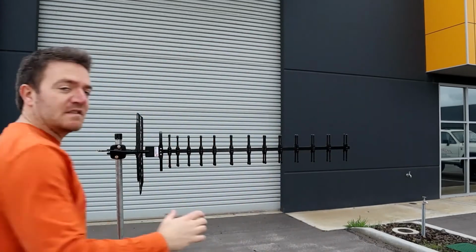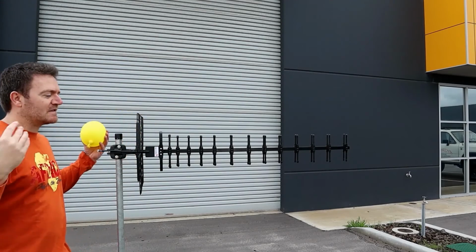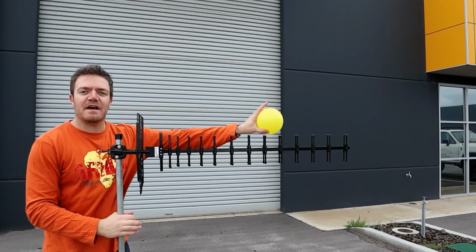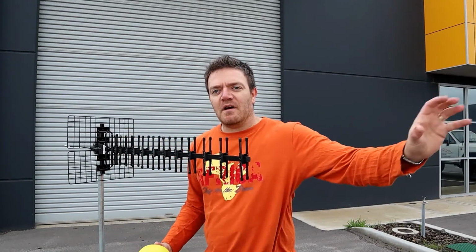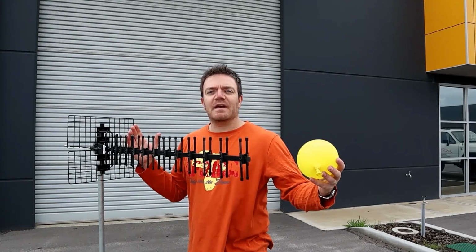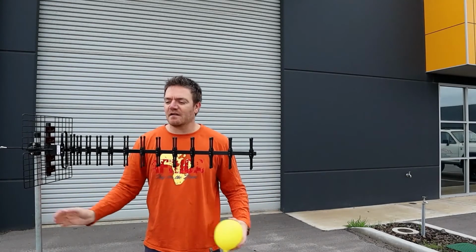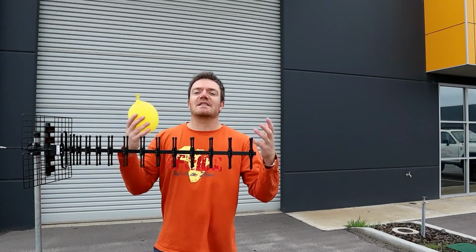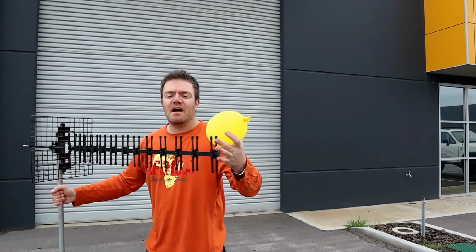Sometimes it's just long elements at the back, but the concept is that the antenna by itself, if you stand on this side, there's not much happening. So this is pointing away from anything sensible. This is the back, so I don't want anything to do with it. I want to go that way, up to the front. So more elements would often make it higher and higher gain, but as a basic rule of thumb, every 3 dB extra gain means you need to go double the length. So if this one is quoted as a 14 dBi gain antenna, as it is, to get to 17, which is 3 more, it has to be double the length. So it gets quite clunky, but this is a good number.